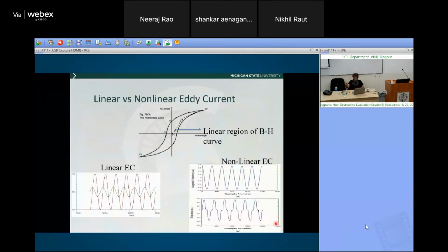The mu itself of the case hardened material is different from the mu of the steel. That's all we know. So you can look at it as a layered media, whereas the case hardened depth is changing, the thickness of this is changing. Total thickness is constant, so the relative thickness of this and this part is different.